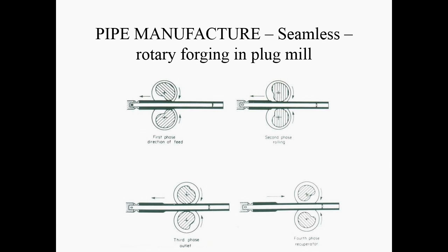And so you're thinning down this tube, and this tube is getting longer while you're doing it. So the billets are often shorter than the final tube length. So you can see it under these points here. We're rolling along, we're definitely in this range here, where we can get a thin tube. But by the time we get to the end, this part here is engaging there, and there'll be a part of the tube near the support which is not actually being thinned down. And you sometimes need to have something to hold. You can imagine then turning that around and then treating this part of the tube. So there are processes where you can do part of the tube in one point and then you rotate it and do the other part in the second stage.